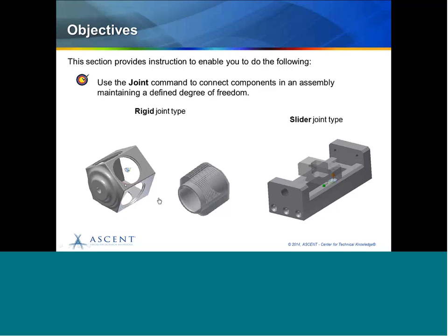This very first video I'm playing is just a simple little rigid constraint. I'm basically selecting my components. I'm going to play that again, selecting the two references on the two components, and it will assemble them together using that rigid constraint.